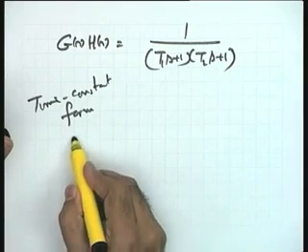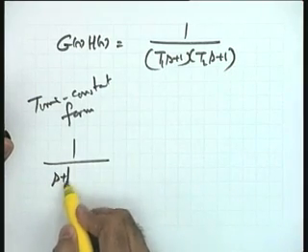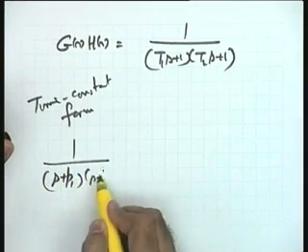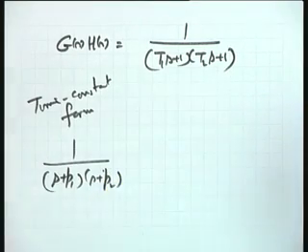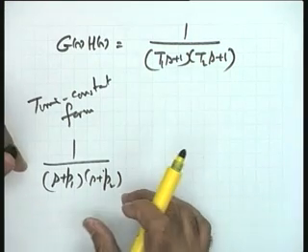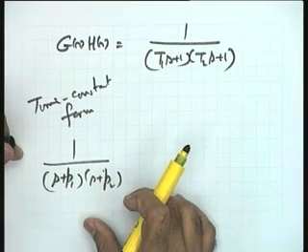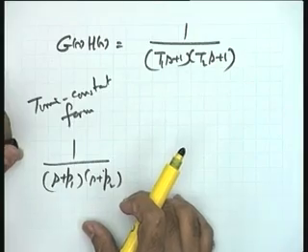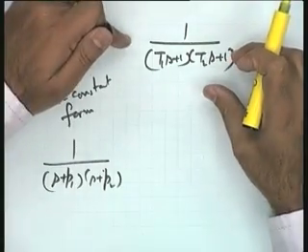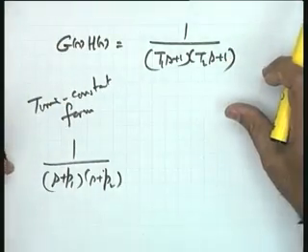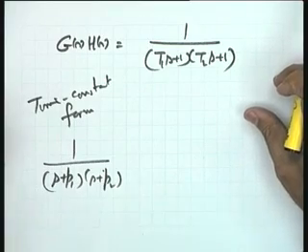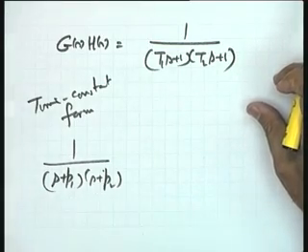You will recall, in the root locus method, the more convenient form is the pole-zero form, because I wanted the open loop poles and open loop zeros to get started with the root locus construction. So this is the pole-zero form of the transfer function, which is more convenient for the root locus construction, and this is the time constant form of the transfer function. As you will see, it is more convenient for any frequency domain method.